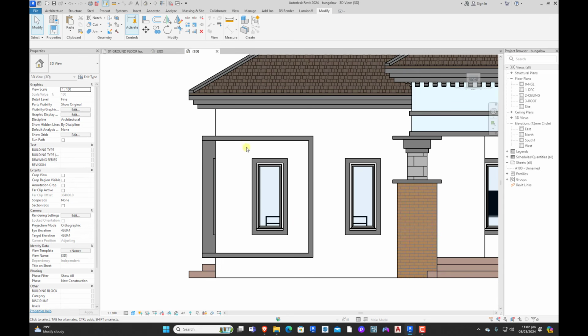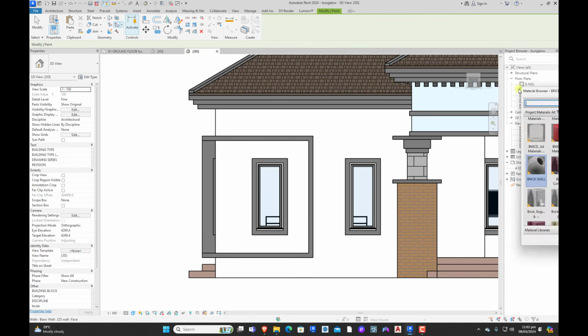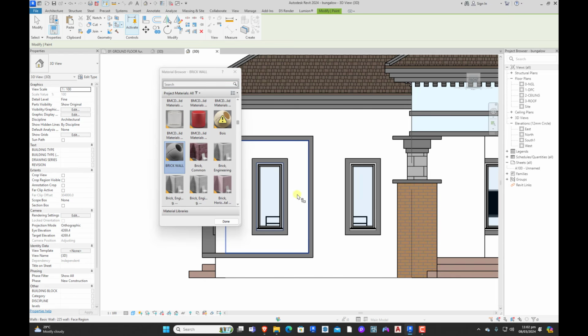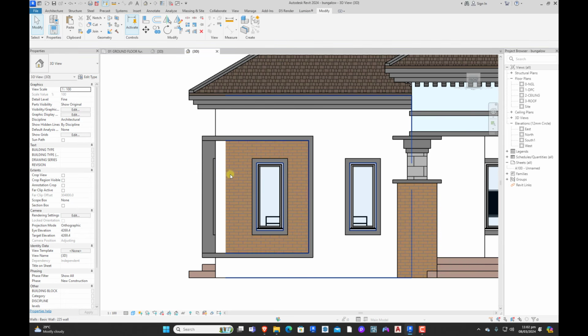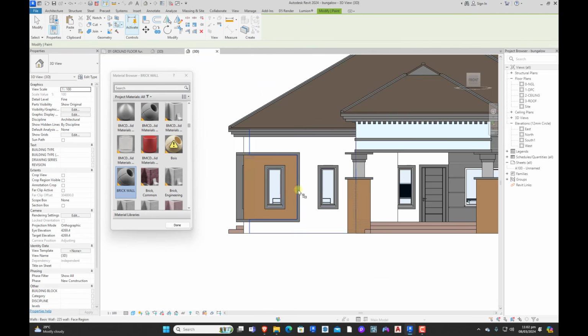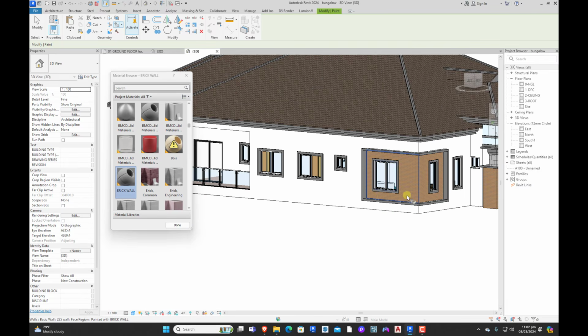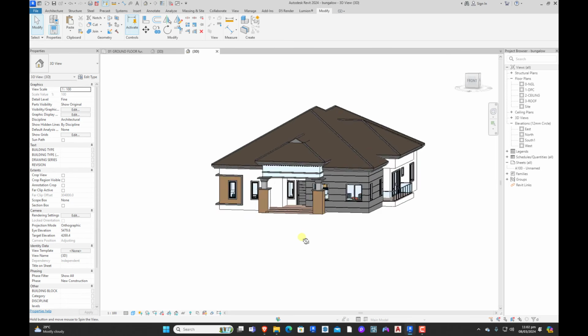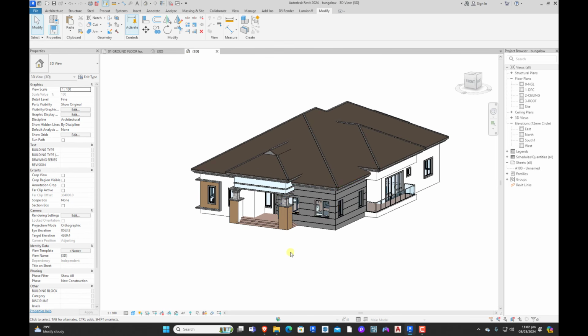Now there's also another place that we need to apply brick on. So we also need to apply brick on this surface. All we need to do is to click on this paint right here. Once you click on the paint, this pops up and you can see brick wall. You can just quickly paint this place, brick wall. Paint here also, brick wall. You turn the building, we also need a brick wall around this corner. So that's that for that. Now you can see how it's coming out, it's looking nice.